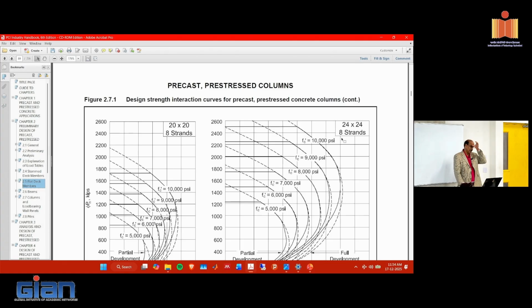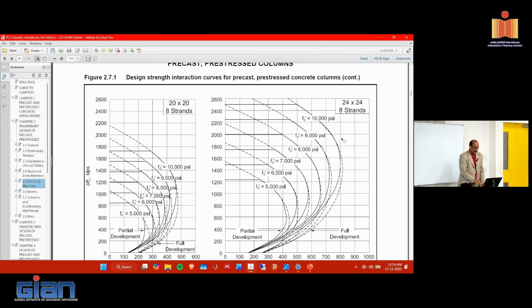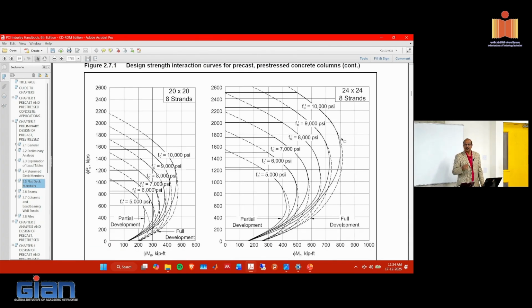So even if they use steel forms, it's easy to insert some foam liner inside to reduce the dimensions. I presume you guys do the same thing. So it doesn't have to be perfectly the dimension that's in the catalog. It's sometimes cheaper to go a size bigger and just use it, but if it absolutely requires, the precasters can easily accommodate those things. So I just wanted you to understand and appreciate the benefit of having a standardized catalog that people can use, every precaster can use.